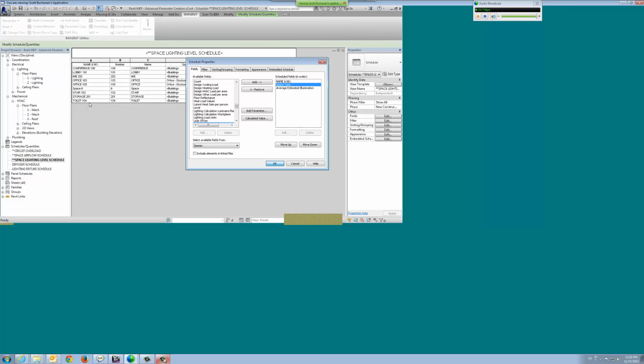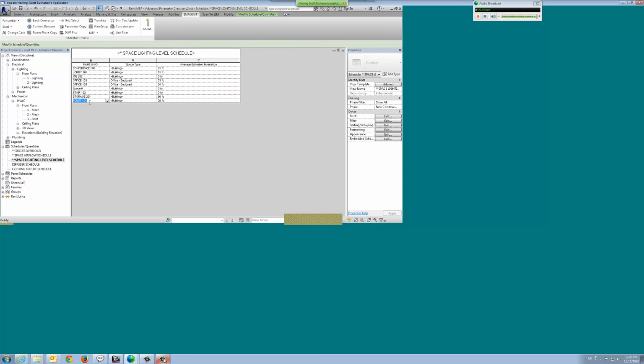Again, this is one of those tools that, if there was a change to the name or the number, you would need to rerun this tool periodically. That way it will go ahead and update. Just like the space update tool. Architects change the room name and number in the Revit architecture model. We need to run that utility. That way it grabs the up-to-date names and numbers as well. So again, that's going to be the concatenator.